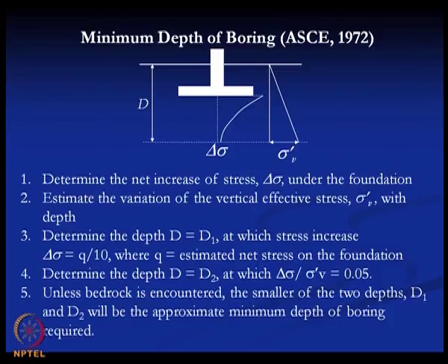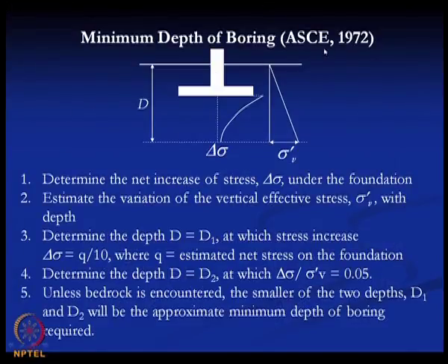Generally the influence zone of a foundation is taken as twice the width of the foundation. That is a thumb rule. But there are some recommendations by which we can determine the minimum depth of the boring. The first one is given by ASCE 1972.